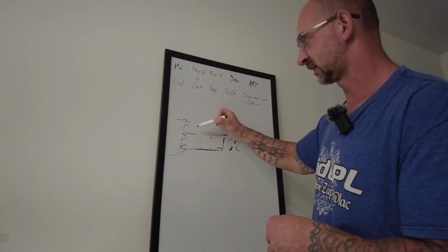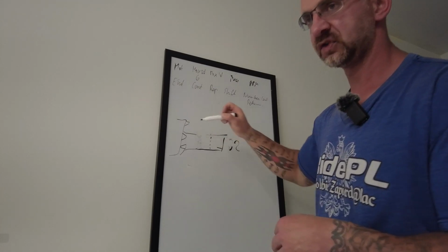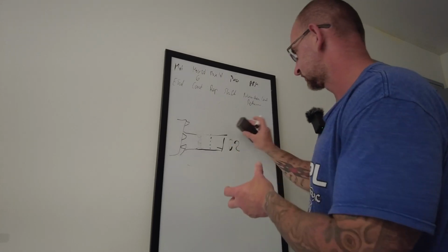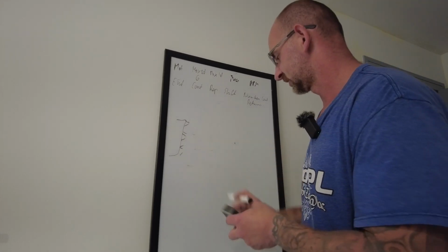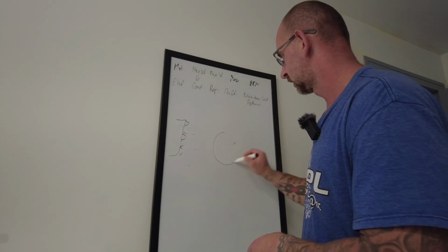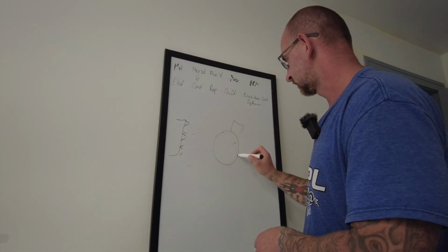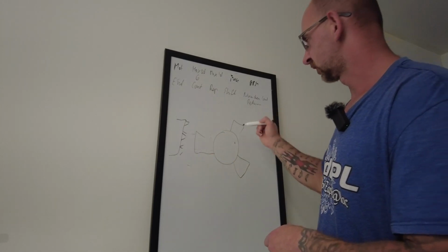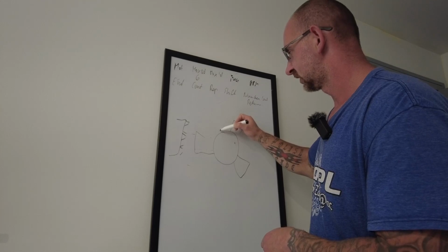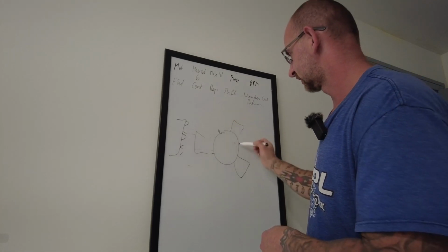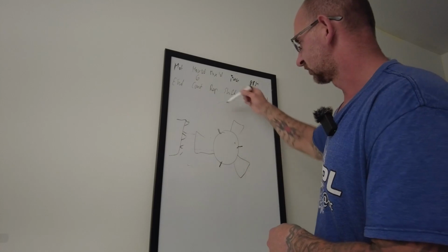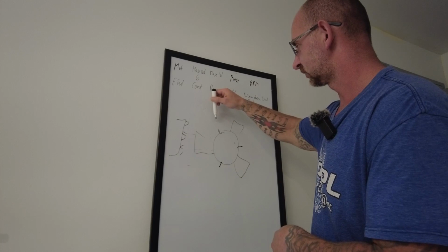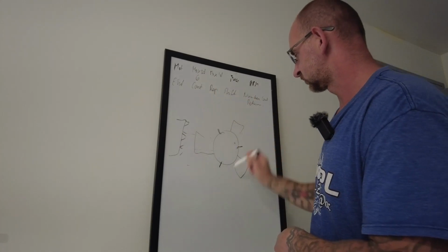Same thing is when you're milling, for example, close to the jaws. I do that sometimes, especially if, for example, you have a feature that's gonna look like this. So you have a part, right? You have your jaws here. And then let's say I got 3 holes, and I'm gonna be drilling those holes, unfortunately, very close to the jaws, right? So I'm gonna have to set my C where the tool comes here, drills, pulls out, it's gonna rotate, and it's gonna hit this one and this one.